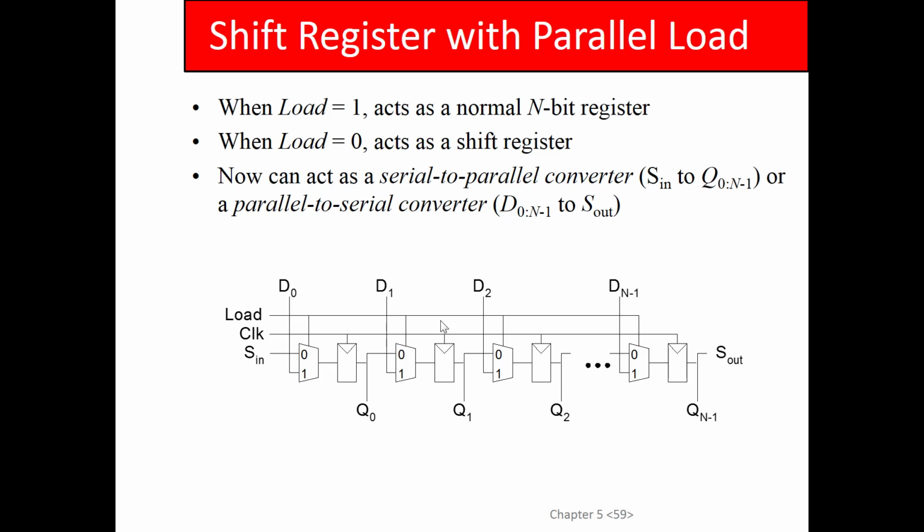And generally speaking, if you had, say, a chipset, a chip that was communicating with a high-speed serial link, you could load in the word that you want to send out in parallel, and then you shift out the bits really fast over the serial link. You guys with me? So this is sometimes called a SerDes, serializer or deserializer. And of course, that would be at the transmitter, and at the receiving end, you would do the opposite. You'd bring in bits serially, and then you read them out in parallel.